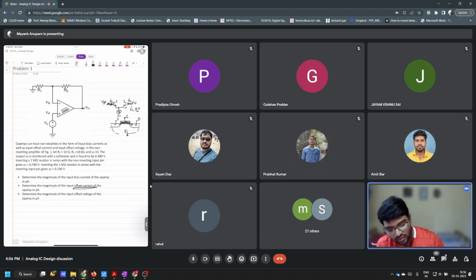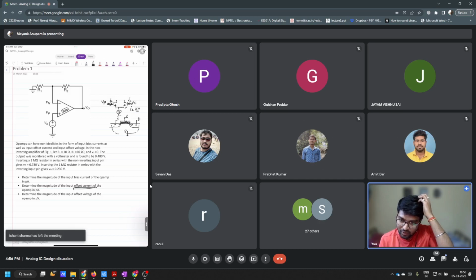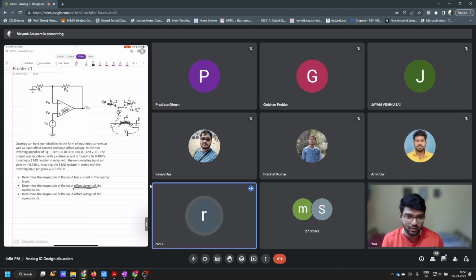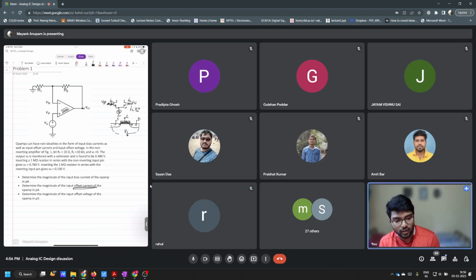Basically, in modern CMOS processes, like you must have heard, 3 nanometer process or 45 nanometer process, something like that, those lengths or sizes, this approximation is not actually valid. There you actually have this leakage current. We call it leakage current, IL, and this also IL. So in that scenario you have these currents.